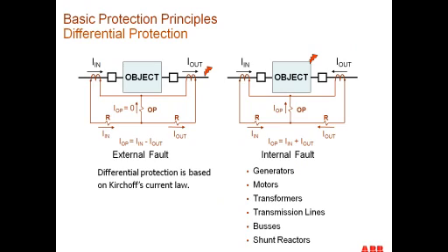The next kind of relay that we're going to talk about is called a differential relay. A differential relay can be used for bus protection. It could be used for transformer protection. It could be used for generator protection. So there are lots of different ways we can use a differential relay. And it's unit protection, which means we only protect between where the current transformers are located.